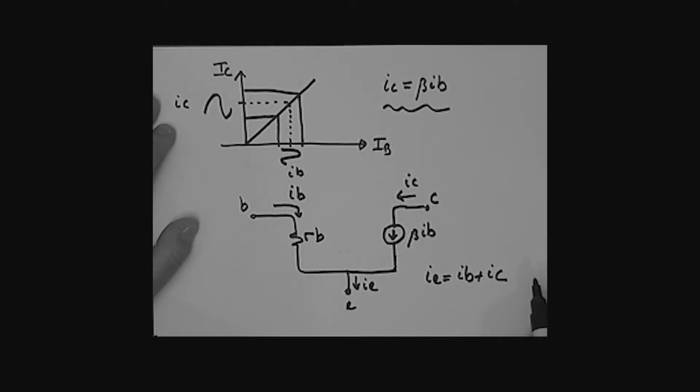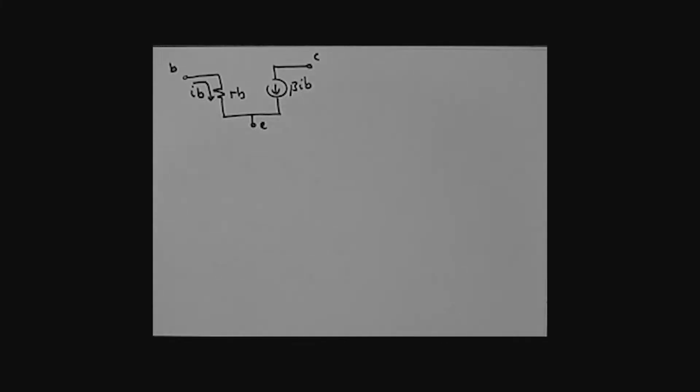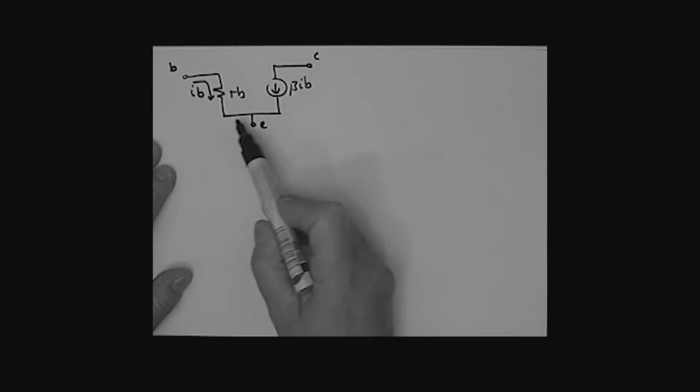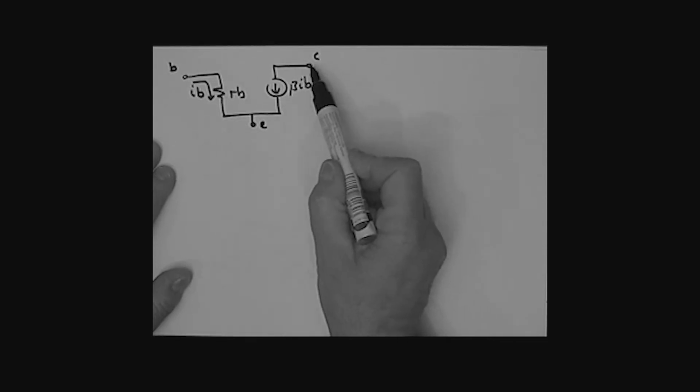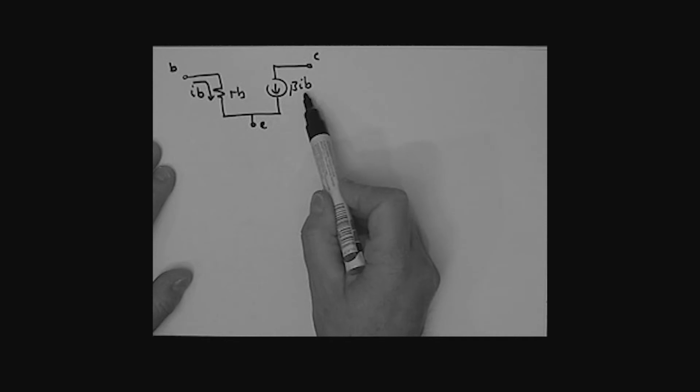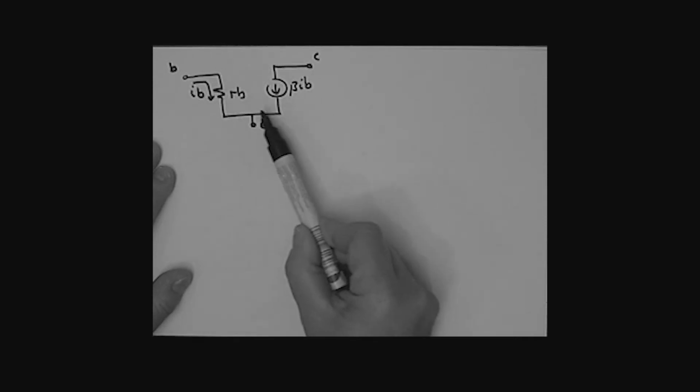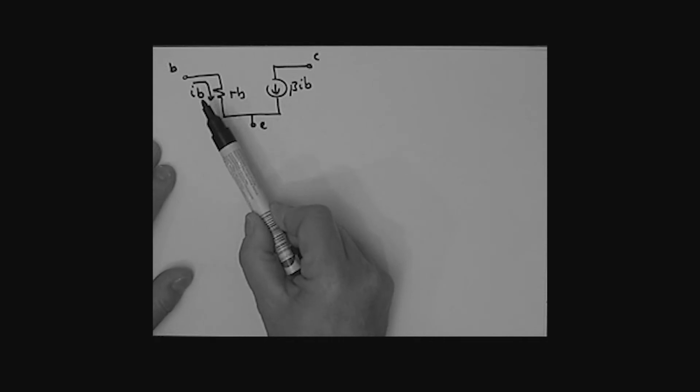The key thing here is you've got to realize that these are AC currents and voltages centered around the DC values. And what we're trying to come up with is an AC model for the transistor. That's what we're really trying to produce here. We really should tie this in to the textbook. Now what I've tried to do here is develop this little AC model very simplistically, having an understanding of the input characteristics for our common emitter circuit, and understanding the collector current relationship to IB. I think you can very quickly and intuitively reason this little model here.